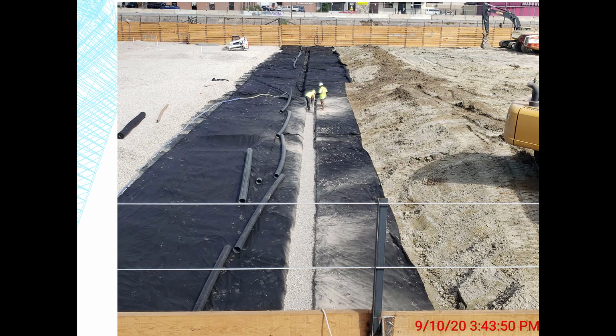Okay, we're back to that same photo we were looking at, and you can see, in my opinion, a really nice construction sequence. You can see that they left the dirt up high. You can almost tell that this is ramped from the photo. So before they've excavated down all this dirt and got into a dewatering position where they have to dewater, they're putting in the dewatering system.